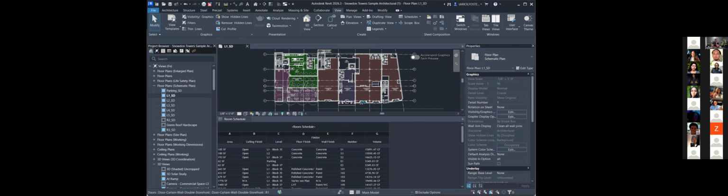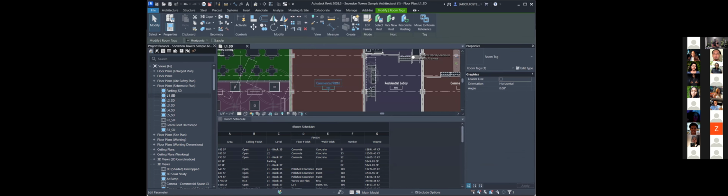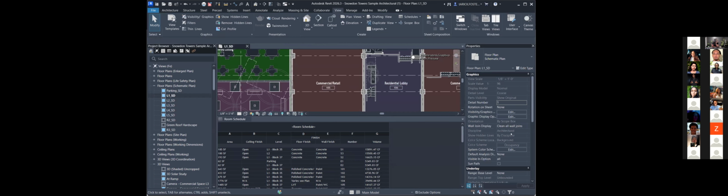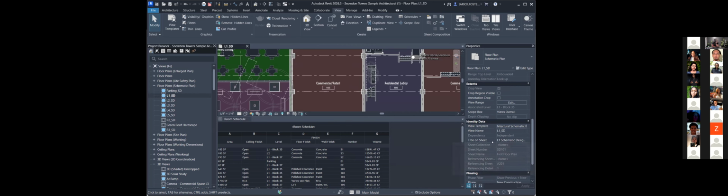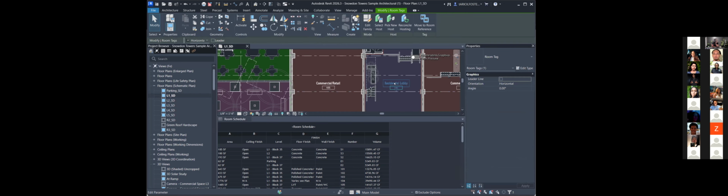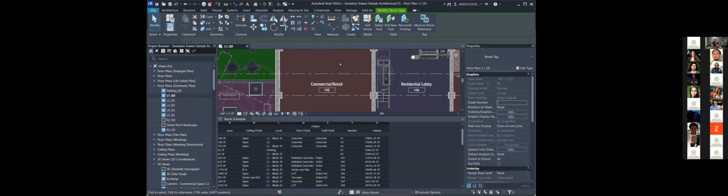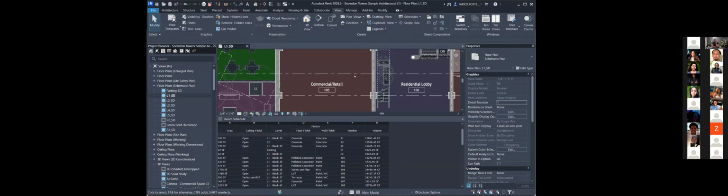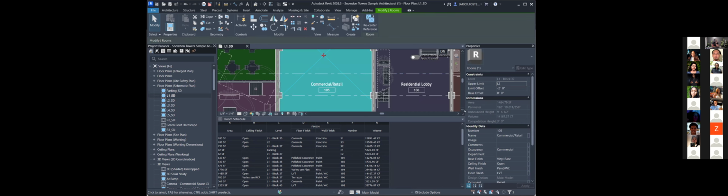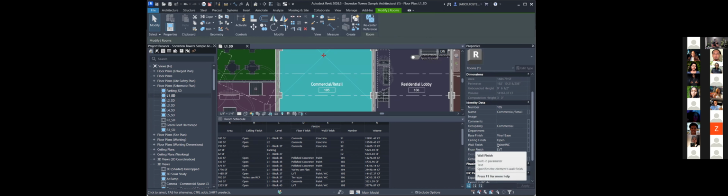So to edit something in this, you can simply select the room that you want to edit. Hold on. You're supposed to be able to see the different stuff. Click it again. That is the title, it's not the room. So in Revit, when you have to select the room, use Tab. There it is. That's the room. Lovely.